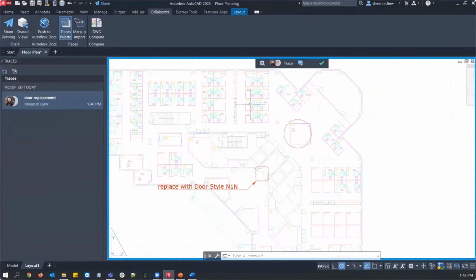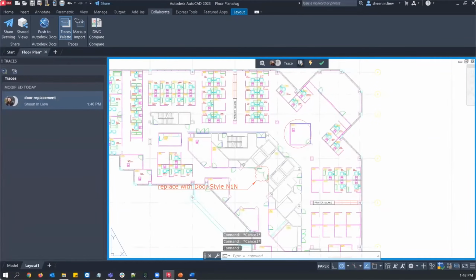So the next mode, which I'm going to show, would be the trace view mode. And in order to toggle to the trace view mode, I'm going to click on the icon that I shared earlier. And once I click on it, you will notice that there's some changes in the display. You'll notice that the drawing geometry is now more clearly visible. And if you look at the trace object right here, it's now looking slightly more faded in contrast. So this is the trace view mode.